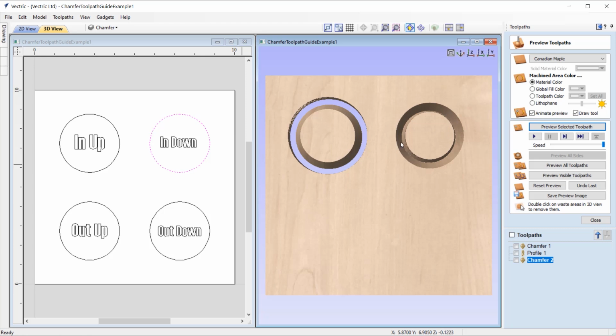And again, we've got a nice clean chamfer there. Now earlier I mentioned that the cut depth of your chamfer relates directly to the actual width of the chamfer and vice versa, all based on the actual angle. And so this is actually quite useful to know what the width of your chamfer is for when you want to, say, mill out excess area that we don't need inside of the chamfer here.